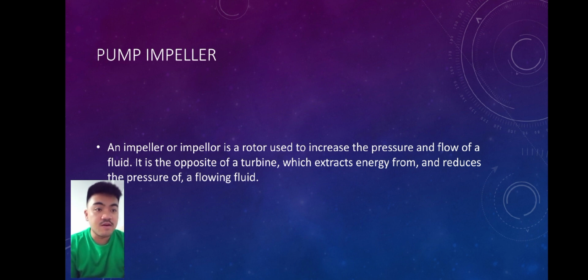The velocity achieved by the impeller transfers into pressure when the outward movement of the fluid is confined by the pump casing. An impeller is usually a short cylinder with an open inlet, called an eye, to accept incoming fluid, vanes to push the fluid radially, and a splined, keyed or threaded bore to accept a drive shaft. It can be cheaper to cast an impeller and its spindle as one piece, rather than separately. This combination is sometimes referred to simply as the rotor.